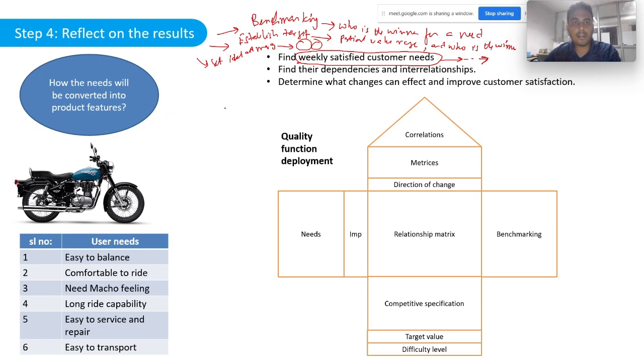For example, when Royal Enfield developed this Bullet bike, it was a city commuter. But if you are designing something more like a cruiser for long rides, now you need to think about a longer wheelbase. For example, this is the bike. Now you have a longer wheelbase because you want to sit in a more comfortable way.